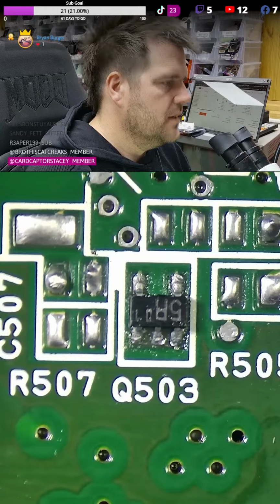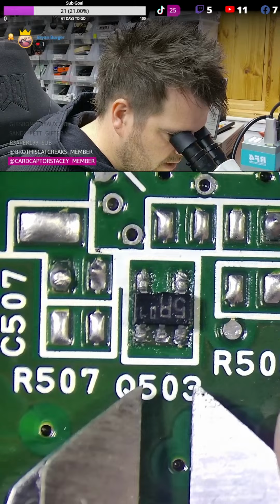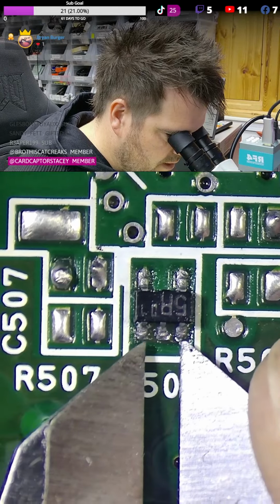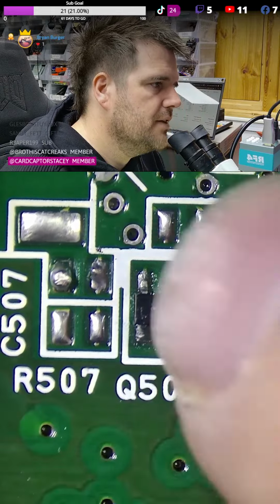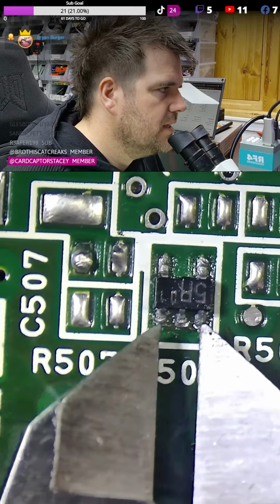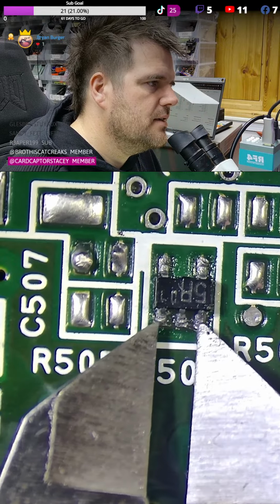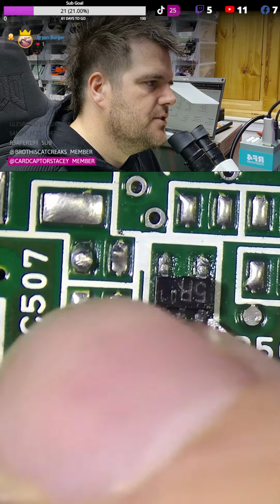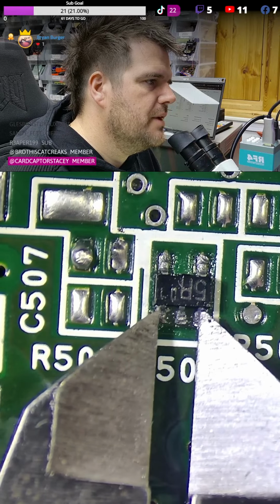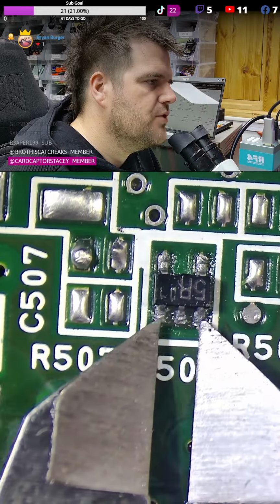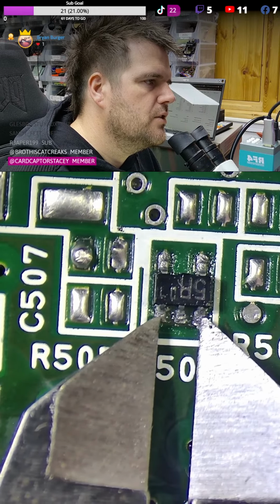So over here, as accurately as I can, I'm going to get my vernier in here. I'm trying to put the inner blade of the vernier on the center line of the metal pad. So see the left tip? I put the left tip on the left edge of the pad. That's the center, and that's the right edge. So if you're looking at this tip here, I'm trying to get that central over that bit there. So that's now center of that pin. And then I'm trying to move this one so the width opens, and basically both tips fall central.